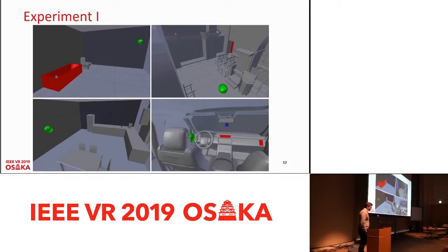So we devised an experiment that looked into computing the dispersion of smells in virtual environments from a source position, that's the blue objects in these virtual environments, given some deviation in this environment, so the red objects are fans, or they could be heat sources, or they could be open doors with wind blowing into the area. And we emit until we reach a certain condition or criteria of concentration at a receiver's point, which are these green objects in these spaces.